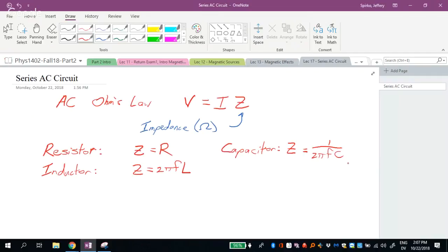That's how our phones know when you rotate the screen, whether you're in portrait or landscape mode. That's how the video game controllers know that you are turning it and moving things around. It's through capacitance. And they make these capacitors really, really small. They're part of the microchip, and they're literally microscopic in size. Inductors, it's more difficult to make tiny inductors because you need a certain amount of magnetism to have an effective inductor. But little capacitors, yeah, we have lots of those.